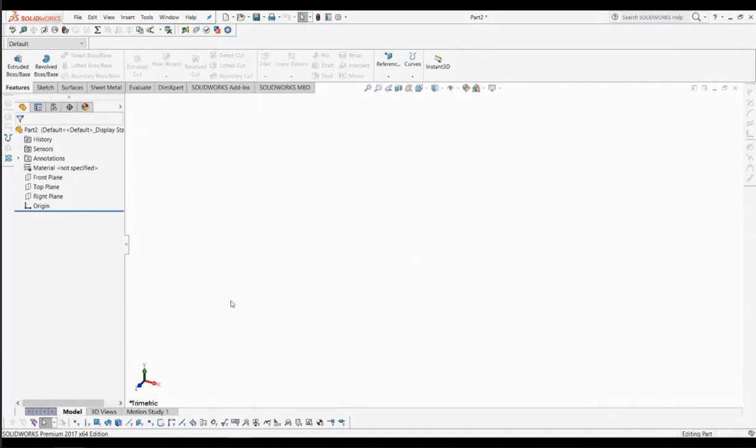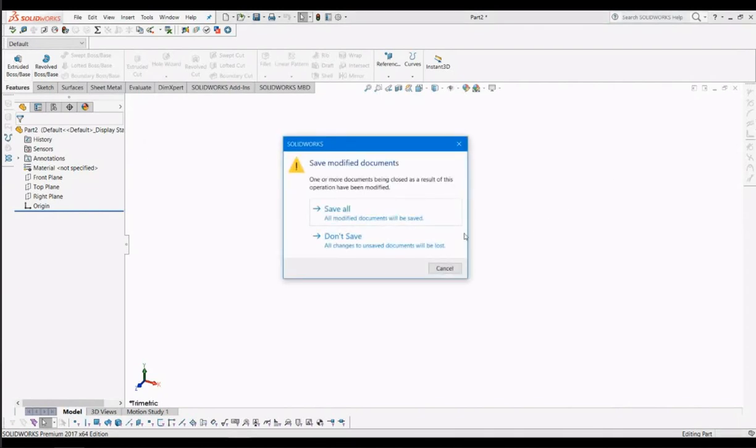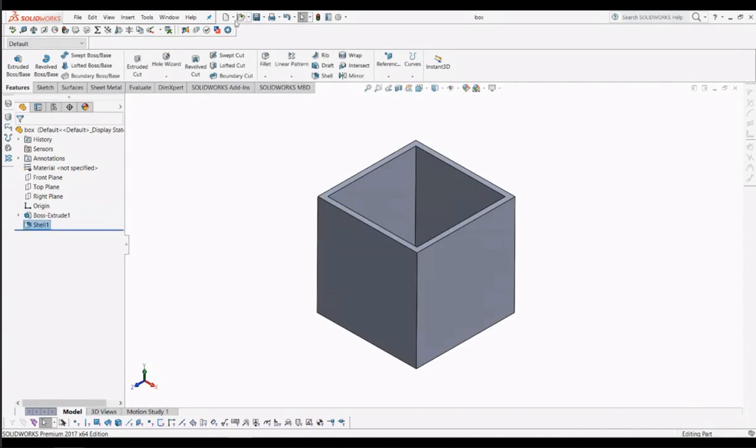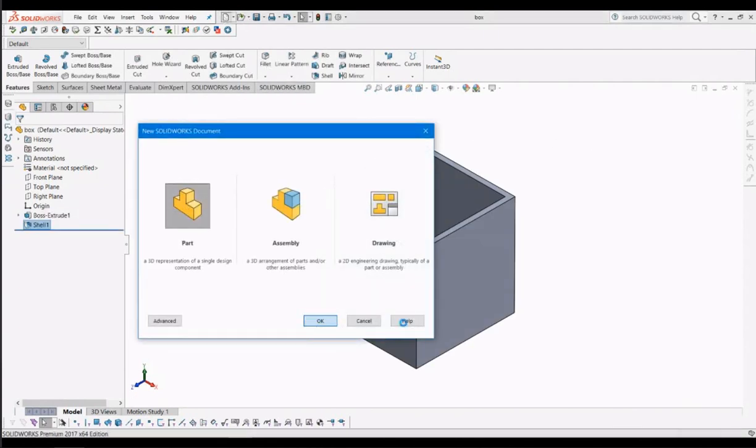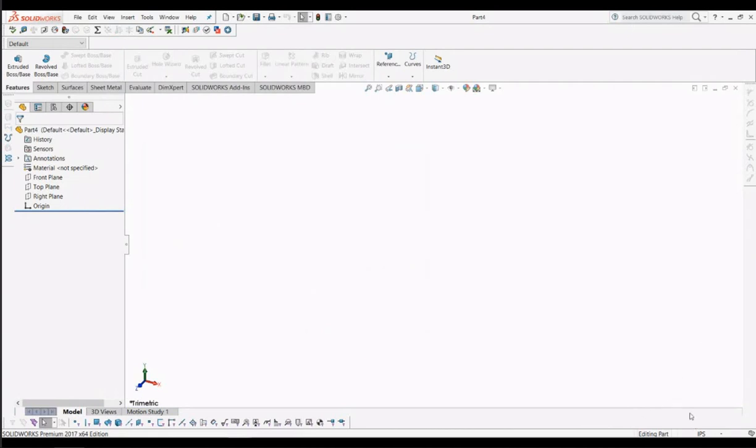After you click that, you can see your part document open. After that, we go straight to the bottom right here, click the IPS button, the unit system button, and change it to MMGS. Now we have already set up the standard unit.